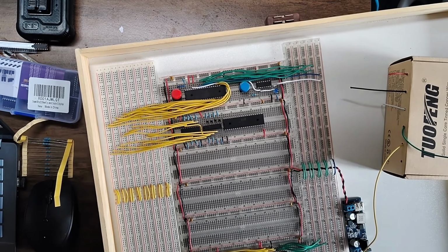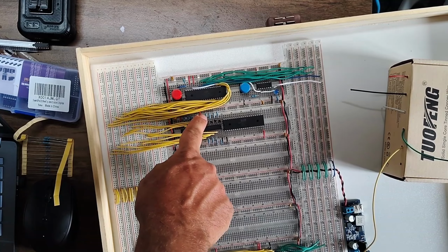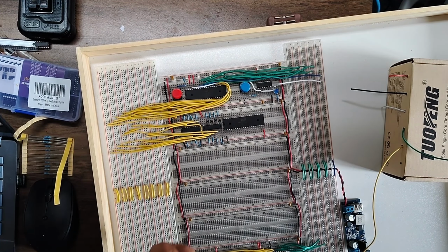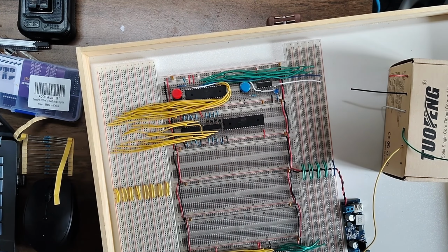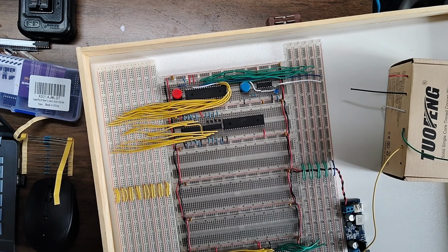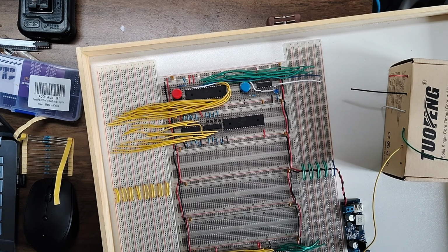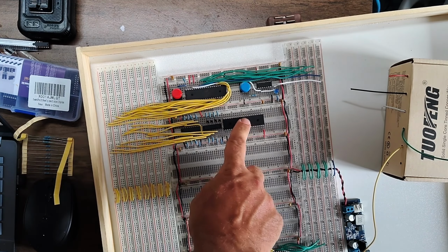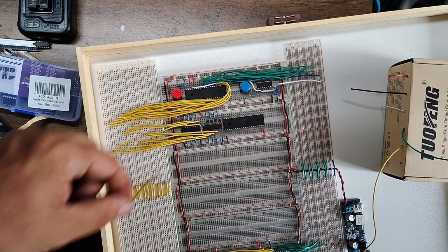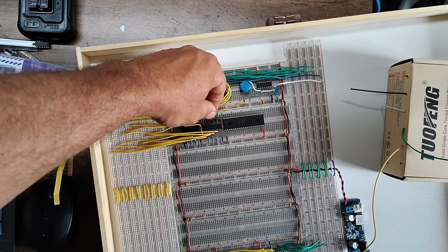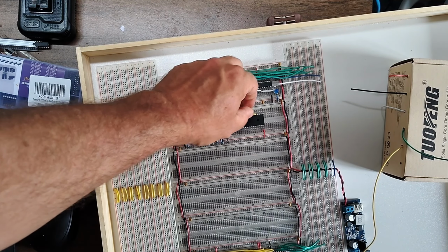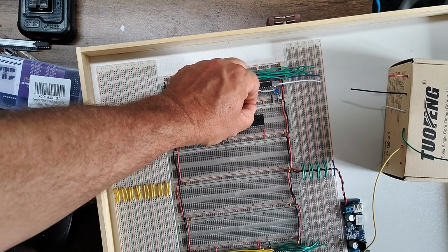And here we are. So I've got these final 4 comparators connected to ground as it happens, and I've just connected them across so that they will always read the same thing. And then the last thing I've got to do is to connect the one wire which, with the correct address, will make this chip light up. So that is the output from this, which I will connect here, and it goes into the chip select bar.